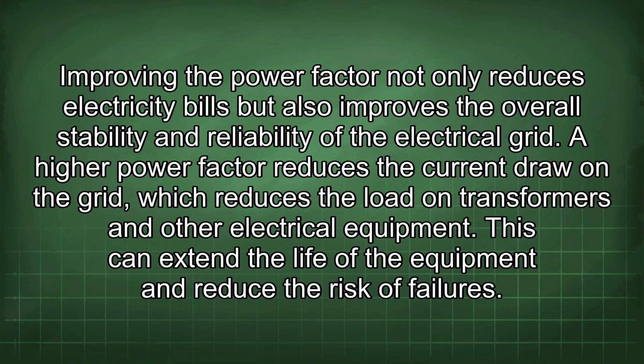Improving the power factor not only reduces electricity bills but also improves the overall stability and reliability of the electrical grid. A higher power factor reduces the current draw on the grid, which reduces the load on transformers and other electrical equipment. This can extend the life of the equipment and reduce the risk of failures.